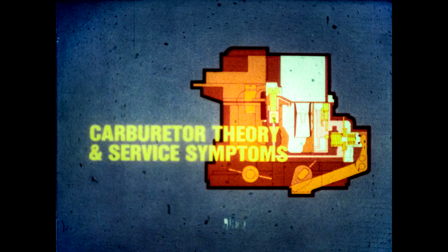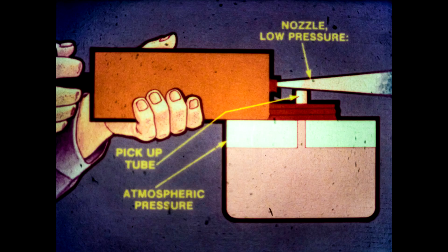Let's examine the inner working of a typical carburetor and see what happens and how. We'll discuss carburetor theory and service symptoms. With minor variations, all carburetors use a pressure difference principle to deliver fuel to the engine combustion chamber. This bug spray illustrates the point. The container is vented to the atmosphere.